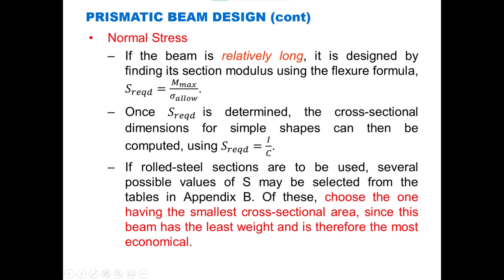You can also test and see by changing the sectional value, whichever is appropriate according to the bending moment and shear force diagram, the shear force values that you are finding. You can change the dimensions, right? You can change the dimensions of the section to suit the required bending moment, to support the required bending moment.